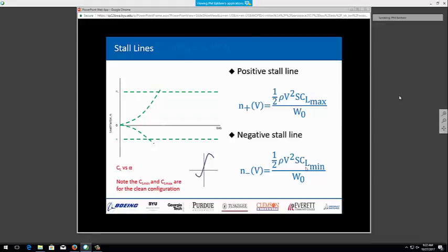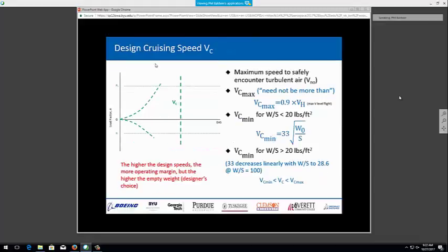So that will tell you where you are within this, and then say, okay, I'm going to look at a condition here at the corner, near maximum G's and near the stall. Having said that, you can get the load distribution from either one of those aerodynamic analyses to begin looking at the structural analysis of your components. So, pick a couple of corner points to look at, and if you can satisfy those, you'll be okay.